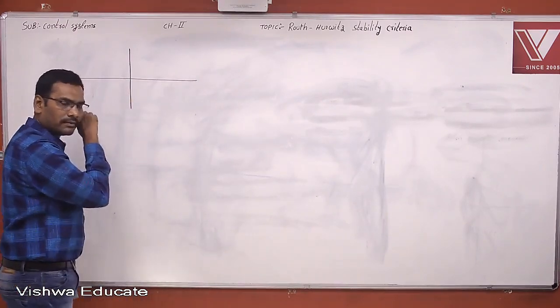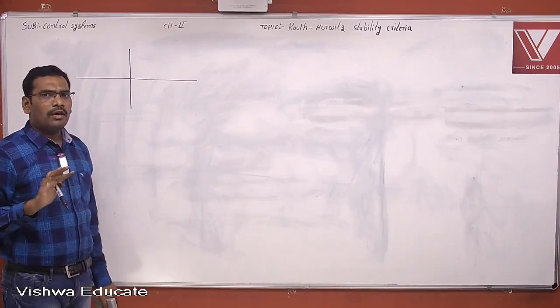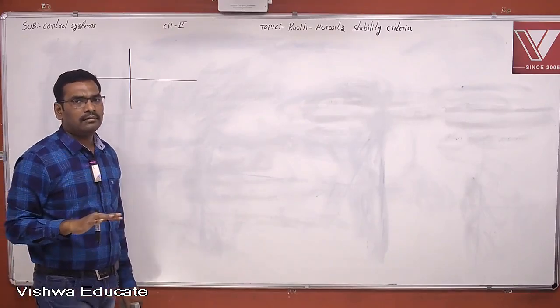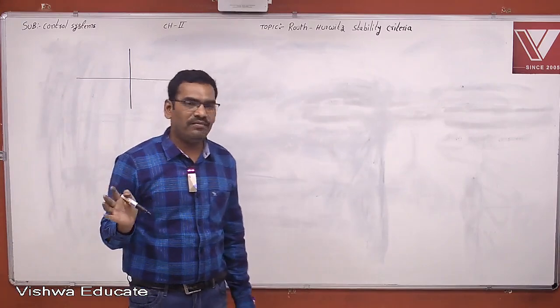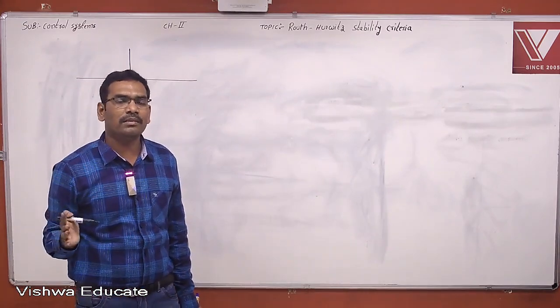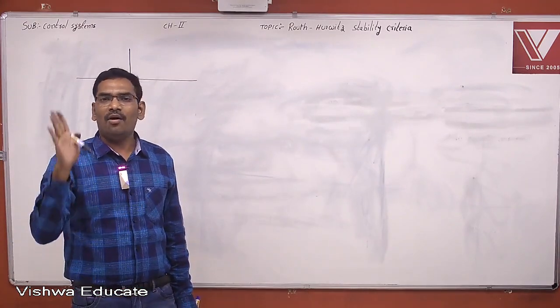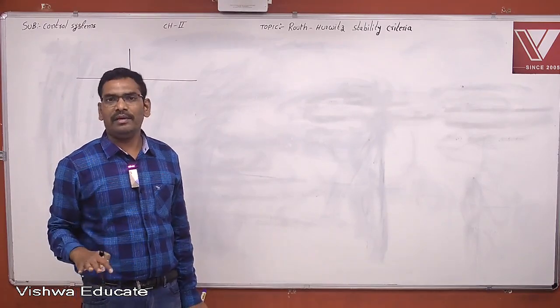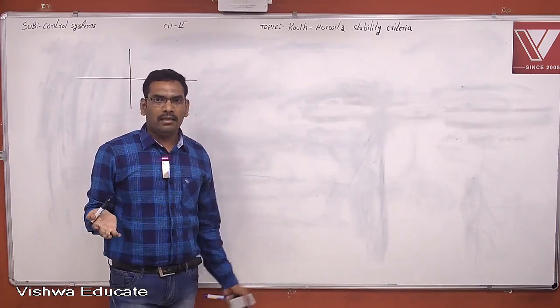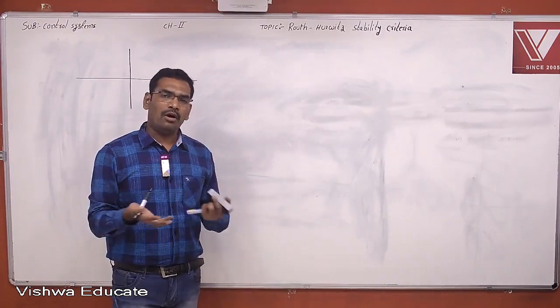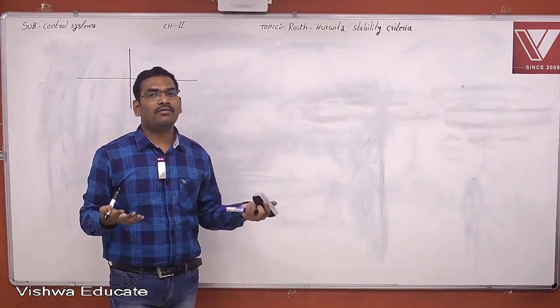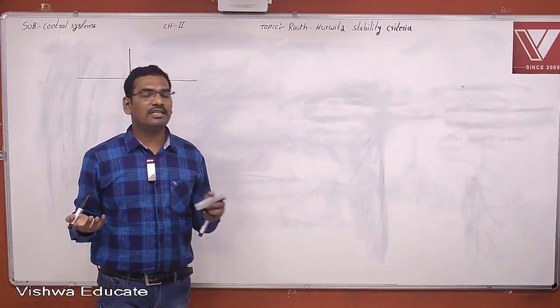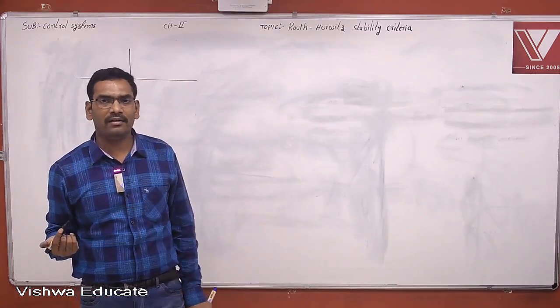Now see here, the row of zeros occurs, and we solve the problems, but in all the problems, all the first column quotient should be positive. Am I not right? We solve the problems, but there is no guarantee of that. Sometimes row of zeros occurs, sometimes sign changes also occur in the first column. Am I right? Yes.